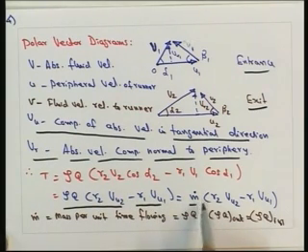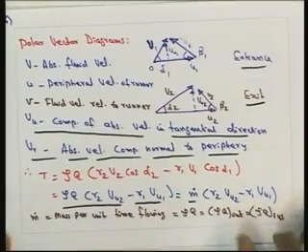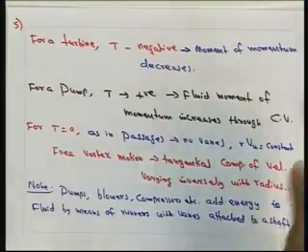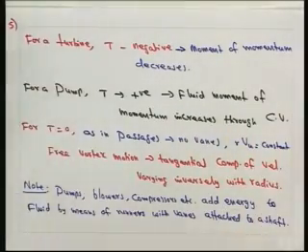So, finally, this can be written as m dot, which is the mass per unit time flowing, into R2 VU2 minus R1 VU1. Now the principle we have discussed here is applicable to the case of a turbine or a pump or a propeller, whatever we consider. In the case of a turbine, the torque will be negative, the moment of momentum decreases. As I mentioned, the fluid with a high velocity is entering the turbine, and that is trying to rotate the turbine.